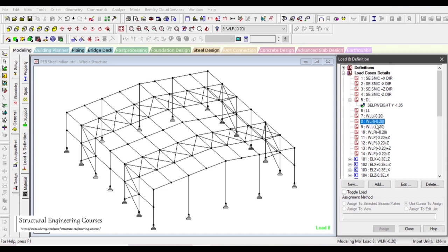So this is wind load from the right direction, keeping minus 0.2 CPI only. This bracket value is nothing but CPI, that is the internal pressure coefficient. And for the external pressure coefficient, we shall refer to the Indian design standard or the values that have been entered. For those who are not using the Indian standard but are using the American standards, I shall explain that also in a separate lecture.